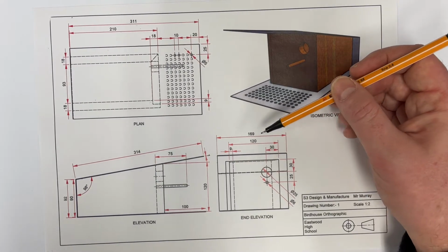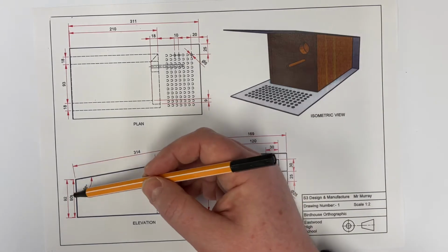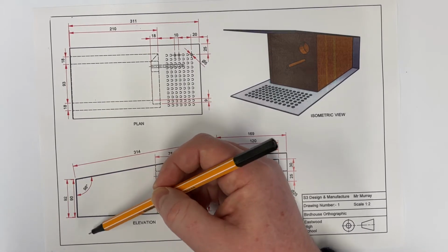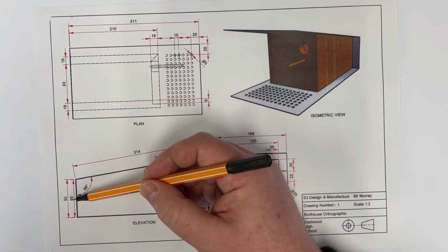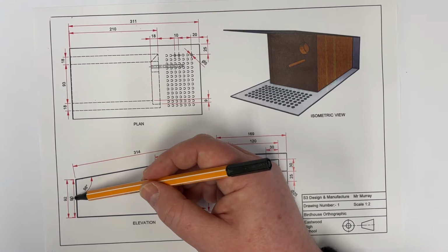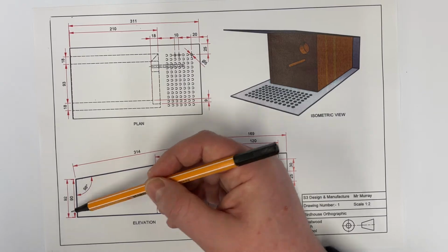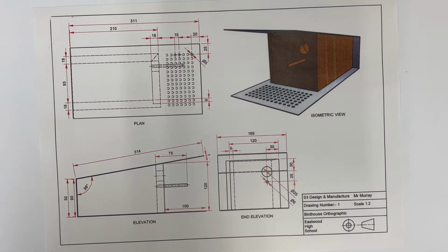And if it's a vertical one to show height, like over here on the left, the number, the size for that dimension would be written to the left-hand side, but as though you were looking at the page from the right-hand side. That also should be above the line and centered over its distance.